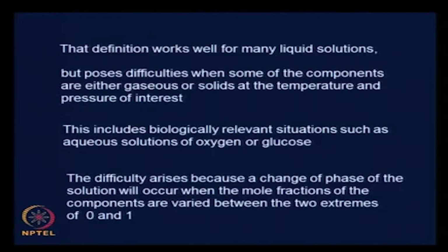Oxygen in water is a liquid solution at the temperature and pressure of interest for growing cells, whereas oxygen itself is a gas. So if you increase the mole fraction of oxygen in the solution to 1, then the phase changes, it becomes a gas phase at higher mole fractions, definitely at a mole fraction of 1, and therefore we need to have a different formulation to be able to handle that.